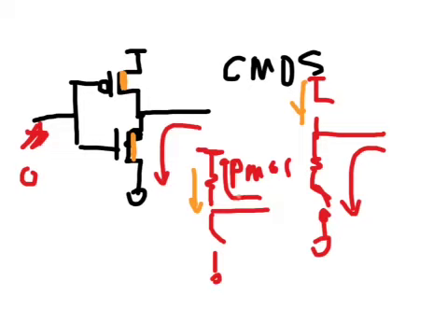So the CMOS configuration is very popular in VLSI design today, because of the unique strong pull-up and pull-down nature of PMOS and NMOS devices respectively, and also as a means to save power consumption. That is, power is only consumed during the switching of the logic gates from logic 1 to logic 0, from one condition to another, and not during standby when the device is holding state. And these are two very desirable situations to have.